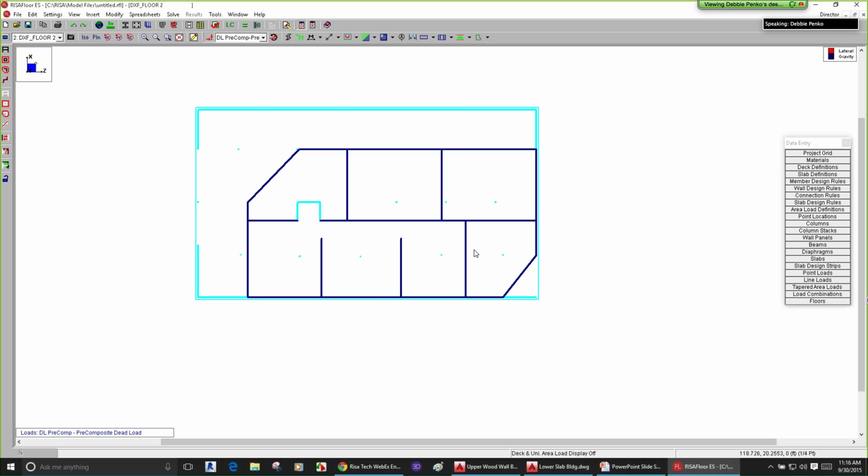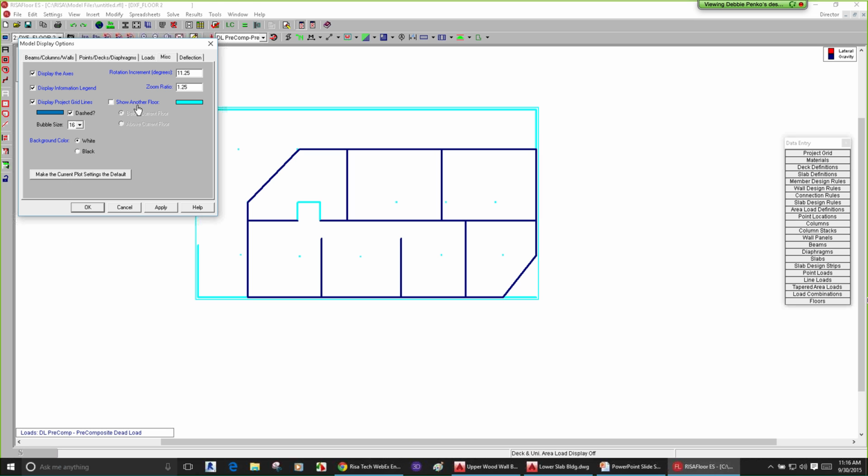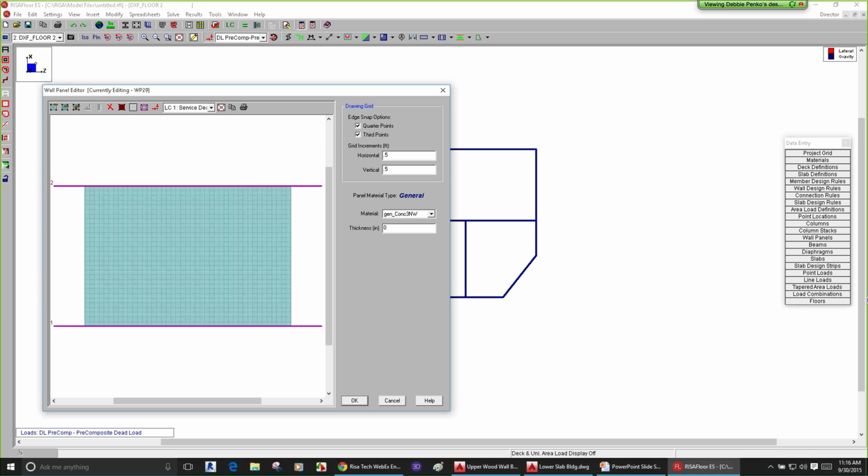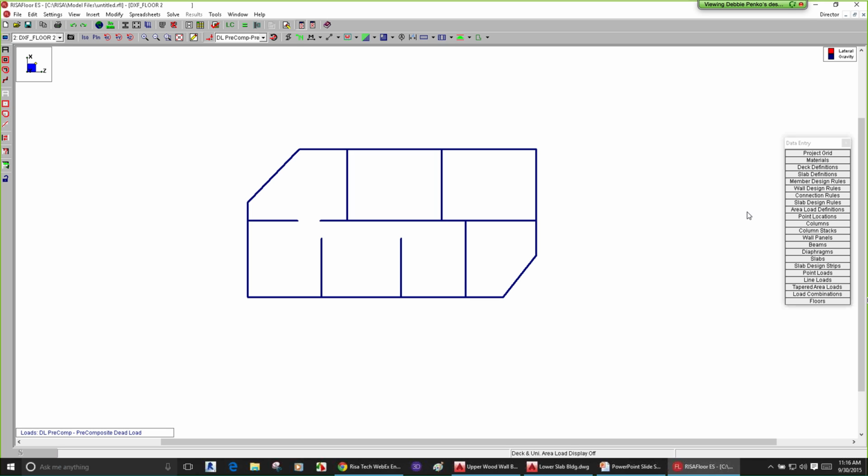First of all, did I land the structure properly on the structure below? That's important. But also now you can see I can kind of trace those concrete walls or masonry walls, excuse me, that I did not import through the DXF. I can do that here in a sec. But let me turn this off for just a second, because what we want to do is worry about what came in. Right now the program didn't know, it's just DXF, so they're just general walls. So we're going to make sure that we tell the program what kind of walls we want to use.